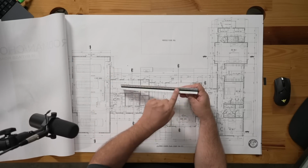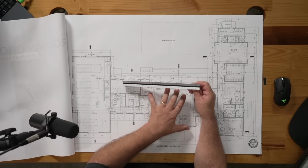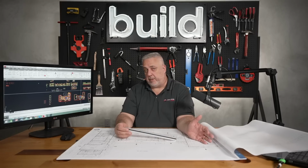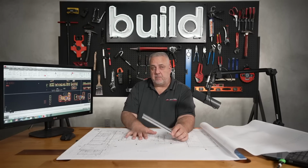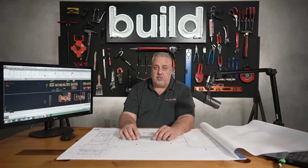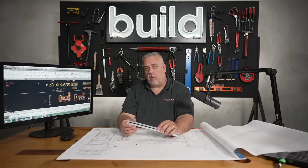So at 1/4 inch scale, the plans are basically at 1/48th scale of the actual building. If I took this plan and multiplied it 48 times, I would get to the size of the actual house. Another way to look at it.